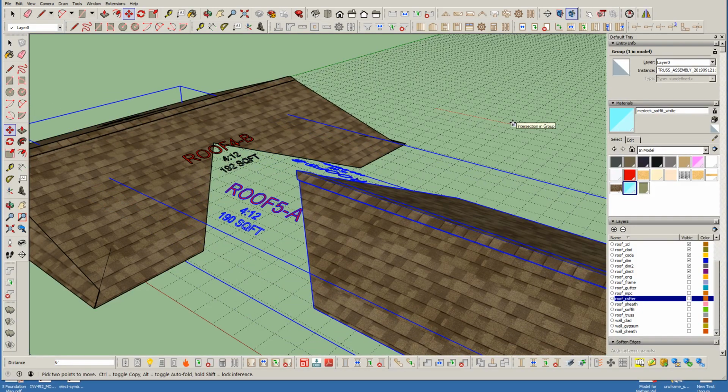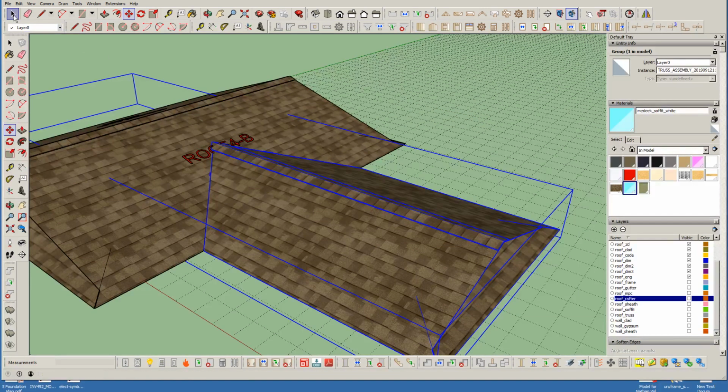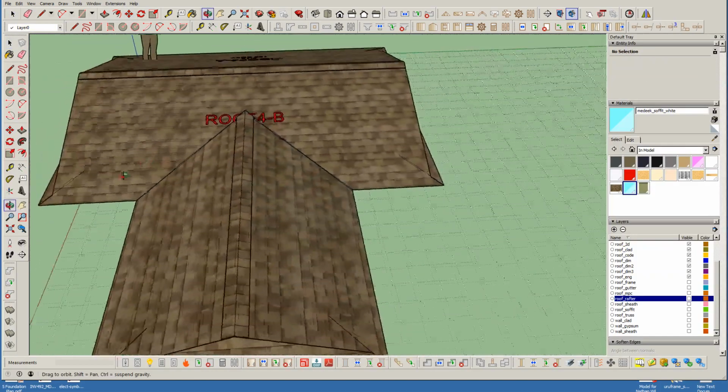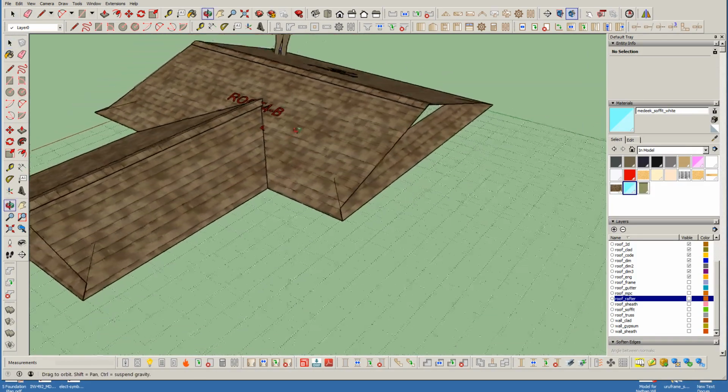And you can see that it trimmed that entity with those two faces and took away that little triangle of material. Okay, so basically that's what you can do right now manually with roof sheathing and roof cladding. You can get there manually, yes, but again, it's tedious, and I agree it's not the optimal solution that we need to have.